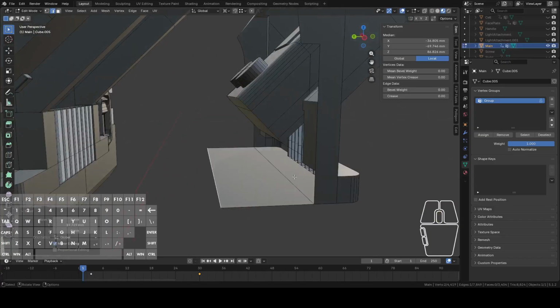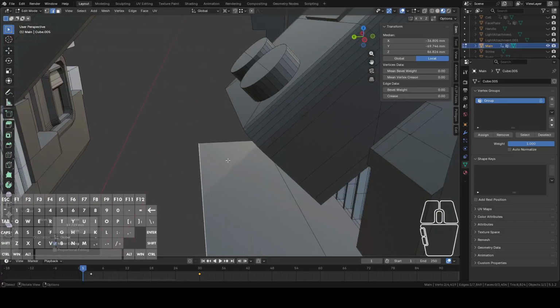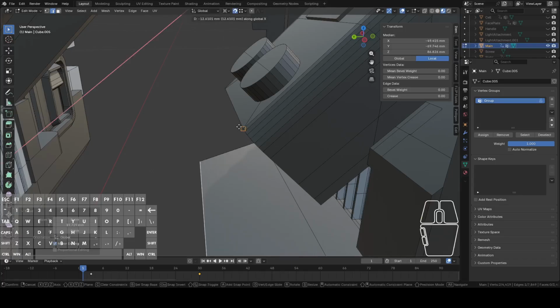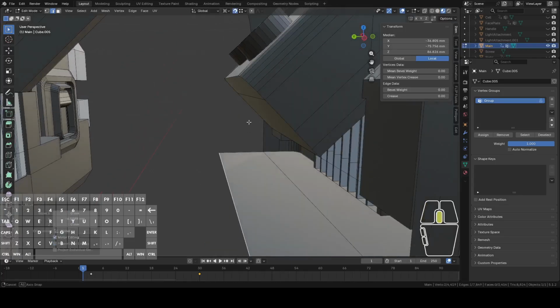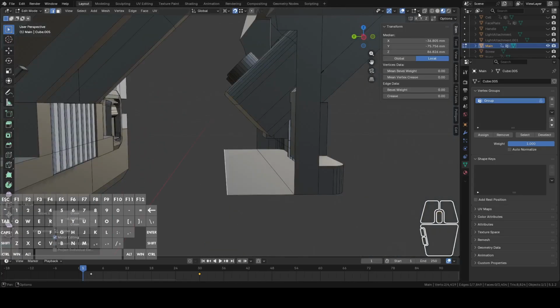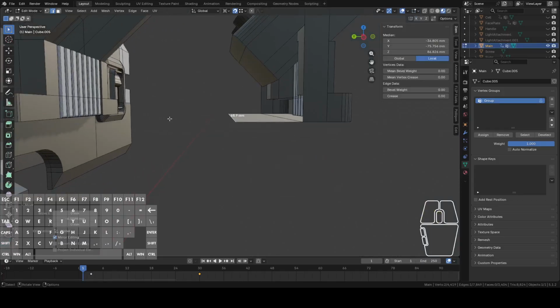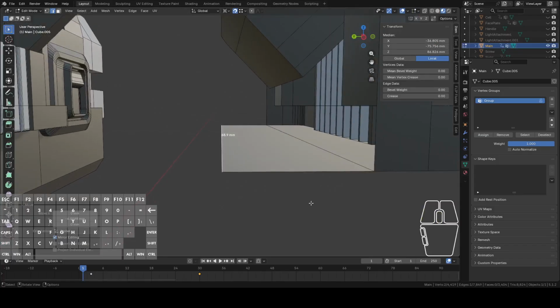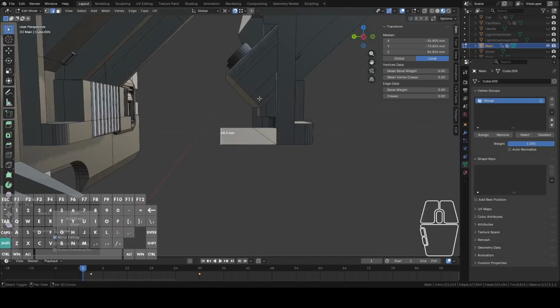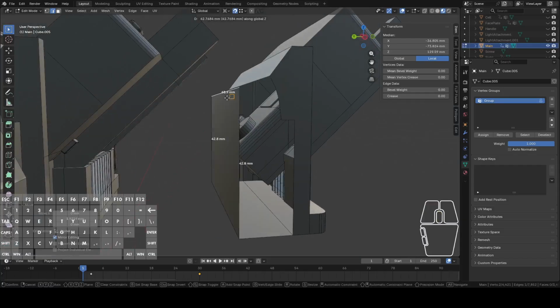I want it to be pretty close to this. GY. And we'll extend it maybe a millimeter or two beyond that because we don't want to dig too deep into the main body, because we're just leaving a big gaping hole in there. So let's pull this up to 13.7. That's GY to 15.7. Then we use E again to go up.